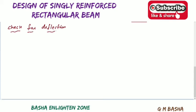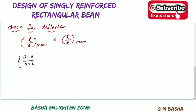It is better to write down the formula for deflection. According to the formula, L by d provided should be less than L by d maximum. So what is your L by d provided? Here our effective span is 3.16 and our effective depth is 0.16, which is 160. That is the provided value. If you simplify, you will get 19.75, and then check the condition.